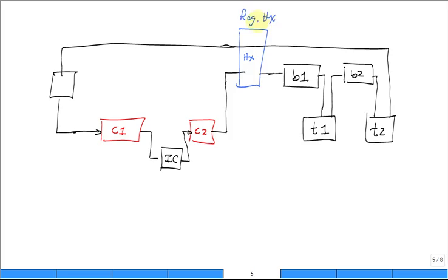Okay. Now let's talk about why you have this burner. Well, it's metallurgical considerations. This temperature right here is some maximum temperature because your turbine's materials can't take that high a temperature. Well, what they do is they bring it up to the maximum temperature, have it drop the pressure but not all the way down, then they take it back up to that maximum temperature.